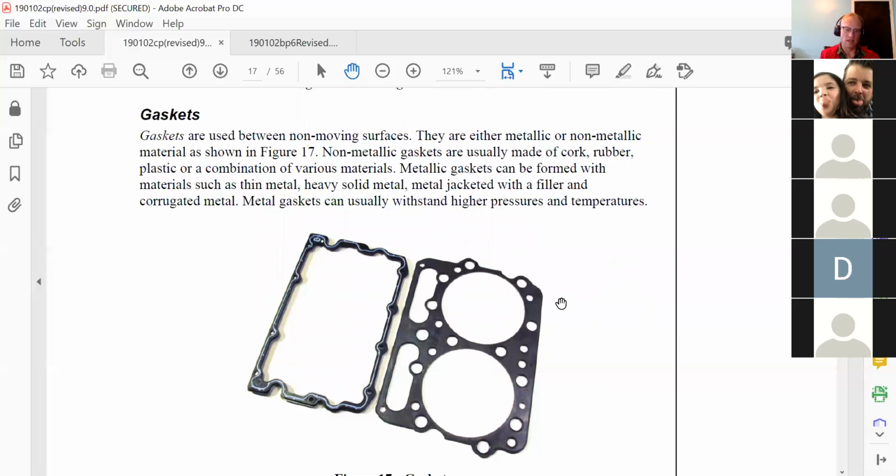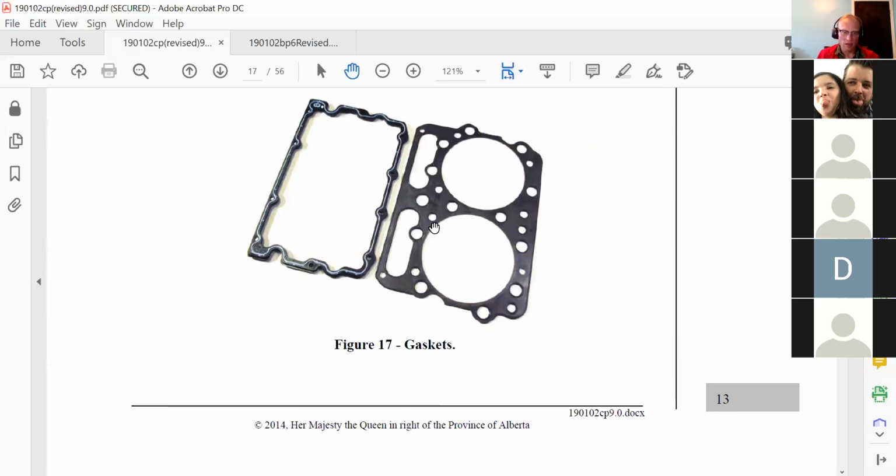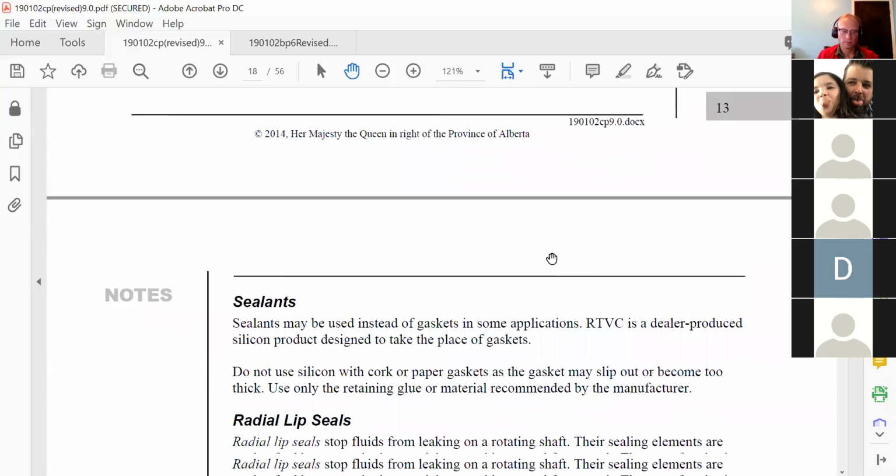You'll have steel, the combustion rings will be made of steel with rubber around where the coolant galleries and oil galleries are, and then different combinations of that will be dependent on where the application is, right? Like I said, your combustion seal might be metal with paper around it, and then you'll have rubber seals around here to seal all that fluid on there.